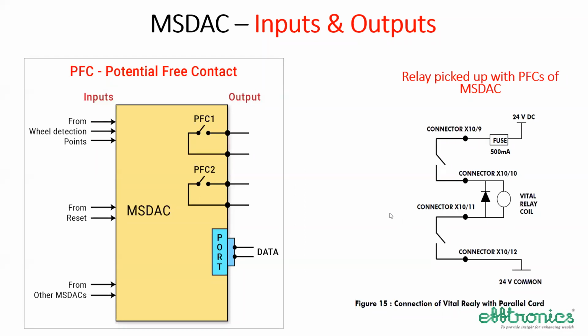Okay, sir. Selva Kumar has asked, the evaluator will come under which SIL category? All are SIL4, including input card, output card, the whole thing is SIL4. As a system, not as a single independent item. As a system, processor card, software, the entire thing working together, they shall comply with SIL4.